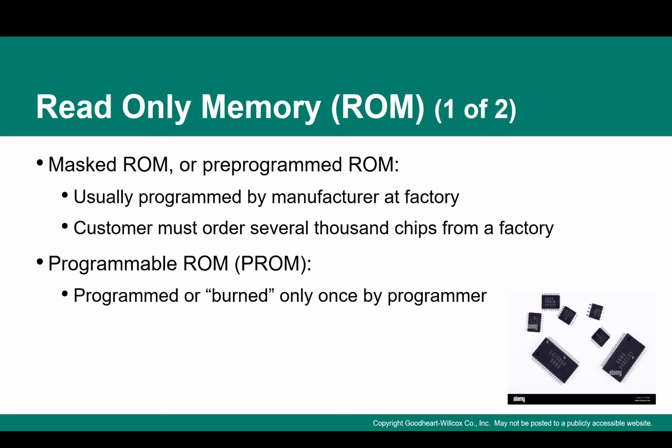When we talk about read-only memory, some of the keywords we've discussed are masked ROM or reprogrammable ROM. What are the features of these types of read-only memories? They are usually programmed by the manufacturer at the factory. The customer must order several thousand chips from a factory, and that's what we mean by masked ROM or pre-programmed ROM.